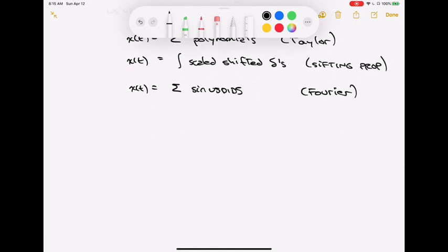We have this idea without proof. We've only just written it, that Fourier said any old continuous time periodic signal can be represented as a sum of scaled and harmonically related exponentials. And we have some motivation as to why such a decomposition is useful, because exponentials have convenient properties when considering linear time invariant continuous systems.